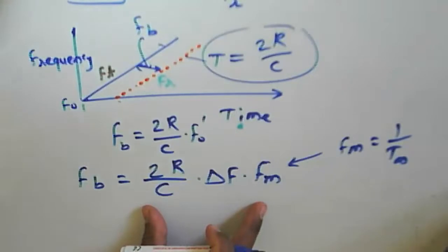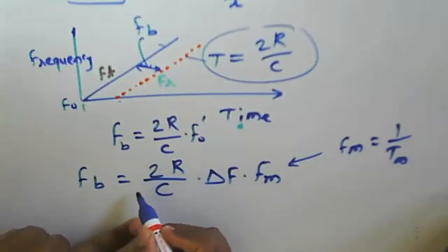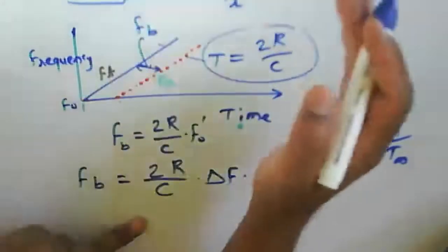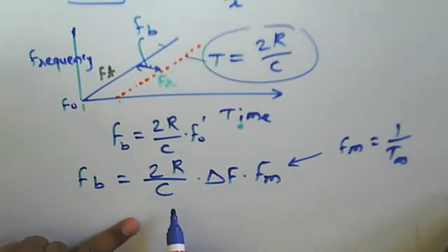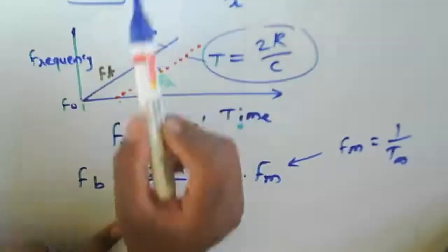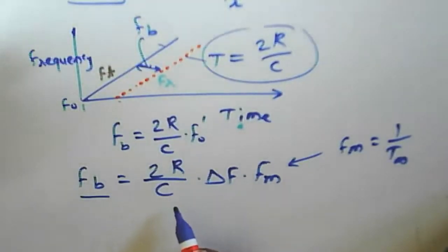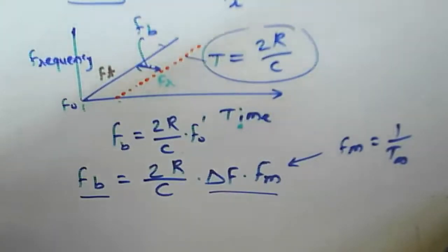and in that equation, this one is the factor for the propagation delay time, or this one is t equal to twice r by c, the transit time from transmitting to receiving the signal. And this way we define here the fb. This fb is the equation for an FMCW radar, and that defines the beat frequency and what will be the range here. This one is for the range, and it is related to your frequency here.